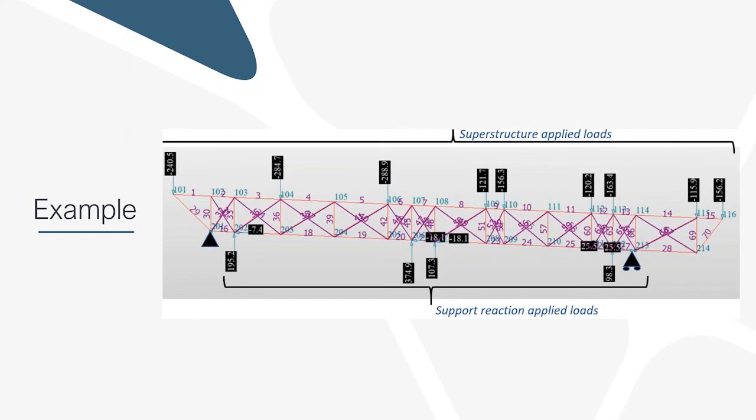And so in this case, the engineer determined the vertical reactions. So they established a pin and a roller, one at each of the ends, because as we know, you have to have boundary conditions to have a model that works. But they calculated the reactions that would be at those columns, and then they were able to modify those reactions in a way to introduce the force couple and make sure that those moments were transferred to the pier cap appropriately and get more accurate results.